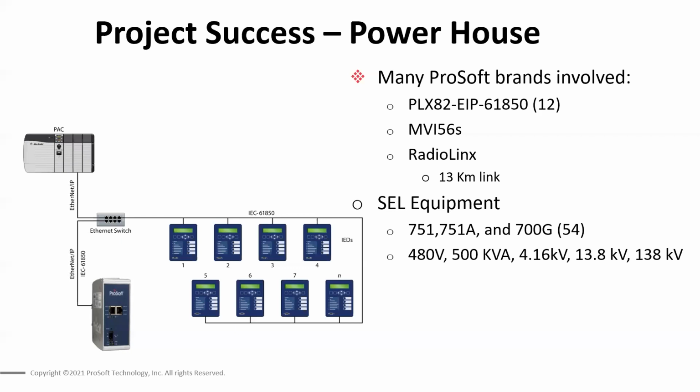If the IED device does not support PRP and only has one NIC, can you still use it? Yes. The question is, if you only have one NIC on the IED, can you still use the new module? The module has the option for simplex mode or PRP mode, and so yes, you can absolutely still use this module with devices that don't support it.